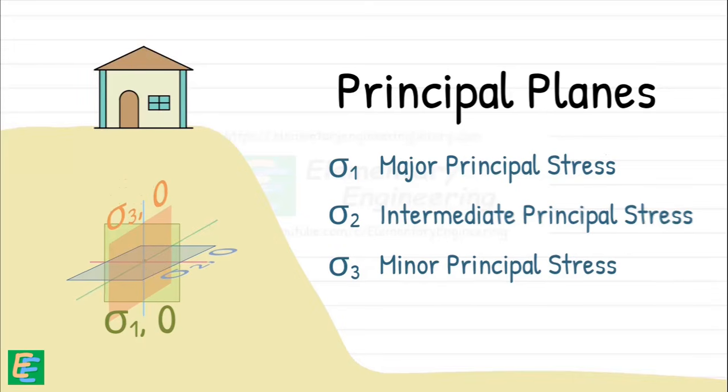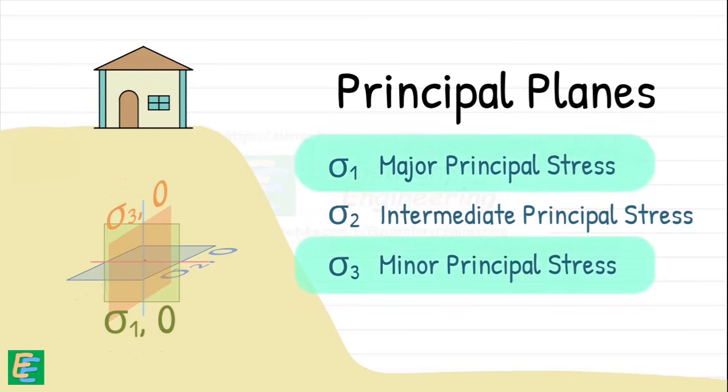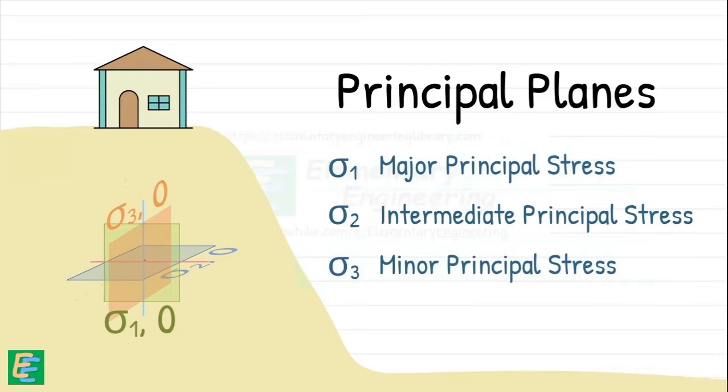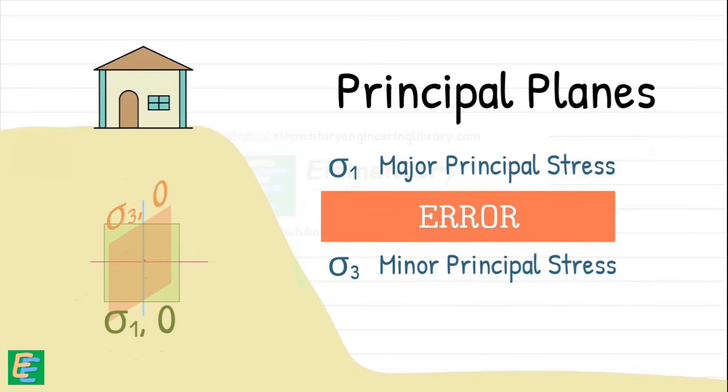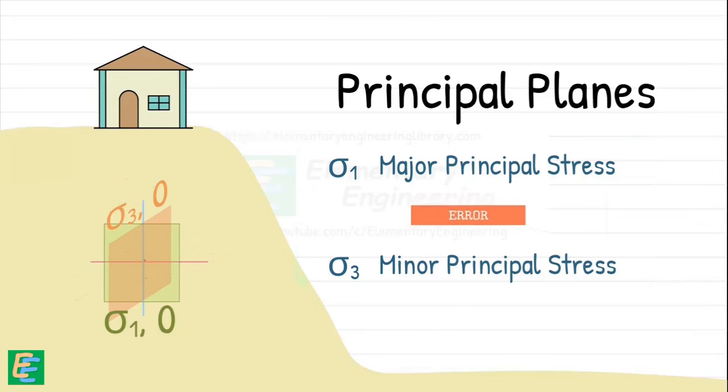In soil studies, it is often convenient and usually sufficient to consider only two-dimensional analysis. This means we focus on major and minor principal stresses and can safely ignore the intermediate principal stress. Even though this introduces some error, this error is typically small enough to be negligible.